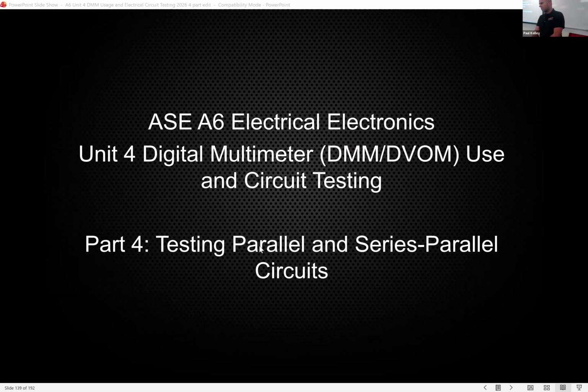The other thing to consider is, you notice I traced red all the way to the resistor on each of the 4. So if I've traced it red, what do you think the voltage should be available right here? It's a full source, right? So 12. What about on resistor 2? 12. What about on resistor 3? 12, and resistor 4, 12.